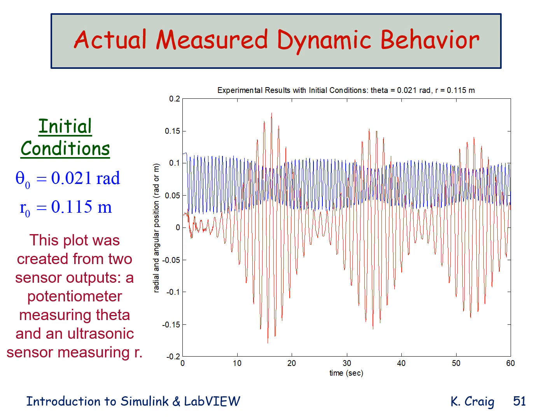One was a potentiometer at the revolute joint of the spring pendulum, and the other was an ultrasonic sensor mounted at the pivot that rotated with the spring pendulum, but measured the motion in the R direction of the mass, so the in and out motion along the R direction.